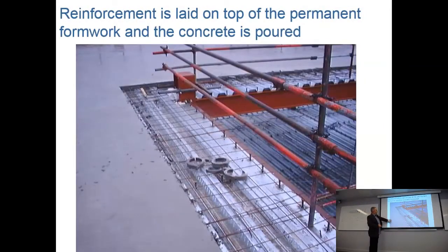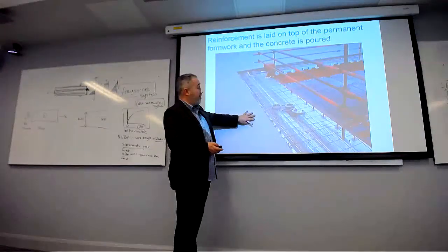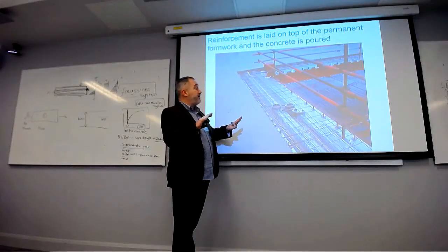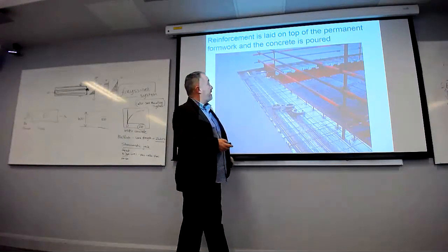And there's an example of where the concrete is on. It hasn't been cast fully across the whole lot, but you can see the concrete. There's some mesh reinforcement in the concrete to stop it from cracking, and then you've got your wriggly tin underneath.